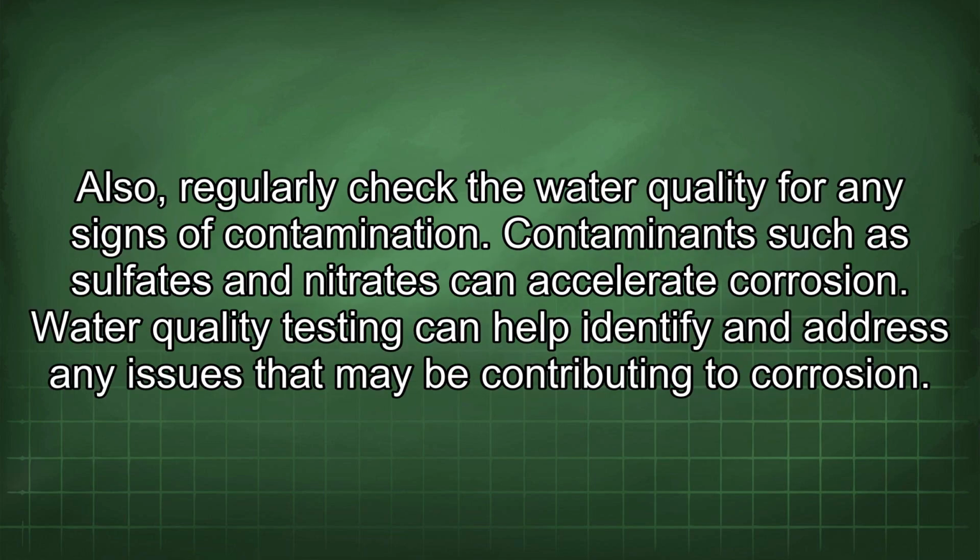Also, regularly check the water quality for any signs of contamination. Contaminants such as sulfates and nitrates can accelerate corrosion. Water quality testing can help identify and address any issues that may be contributing to corrosion.